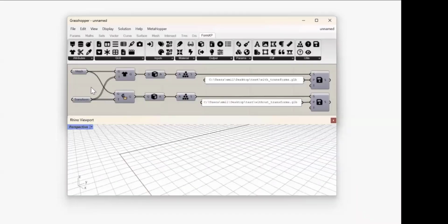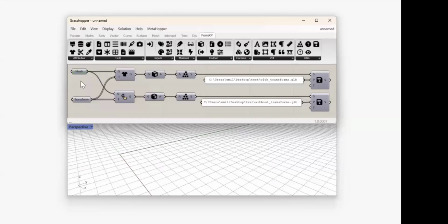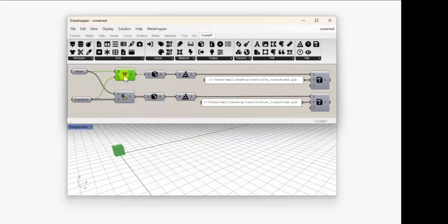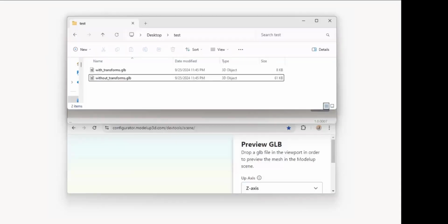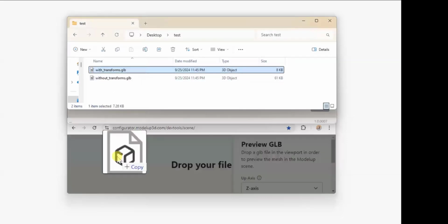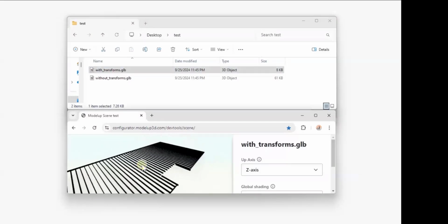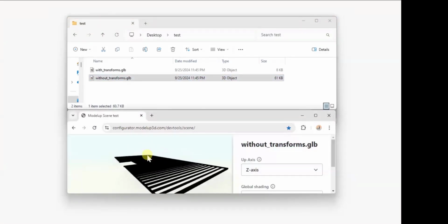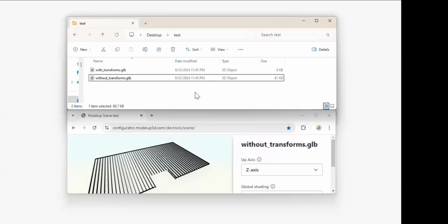And speaking of file size, here's a concept that we use a lot: transformations. So here's an example in Grasshopper. You have a cube mesh, and then you can apply a bunch of transformations like stretch, translations, and so forth. And using those techniques, you can build up more advanced models. And instead of applying these transformations and outputting 50 different meshes, you can actually output one mesh with 50 transformations. So if you now save the two geometry files to compare, you can see that the one with transformations is 8 times smaller. And that makes sense, because transformation matrices are much lighter than meshes.